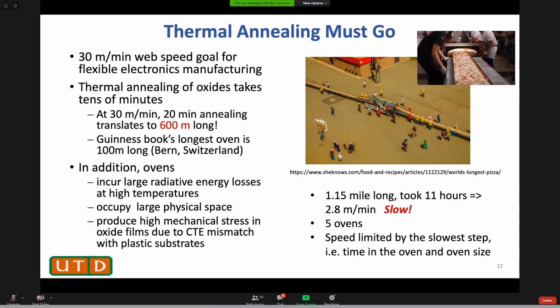So this is a picture of photonic curing. It shows SEM of some metal ink. This is sintering a metal, and you have a flash xenon lamp shining on it, and basically, the metal nanoparticles melt and sinter together and form a conducting pattern. Most of the existing applications are making metal conducting patterns on PET substrates.